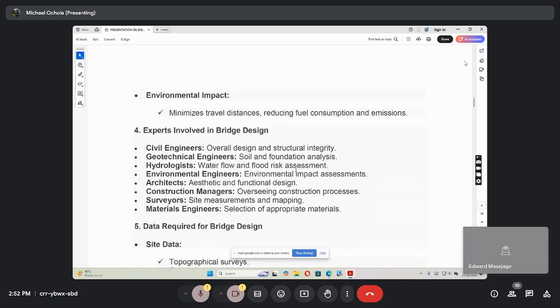So what you do is, if the road is at a super elevation, if the road is going down, is going up, the grade is sloping up and down, the bridge must depict or reflect verbatim the shape, the geometry of the road, the profile of the road. This is what I need to know. Otherwise, don't go and design a bridge always with the same support height, abutments all the same height, 10 meters. No. If you are sloping up, the first abutment may be 10, the next one with the slope given might be 10.25 or 11, depending on the slope of the road.